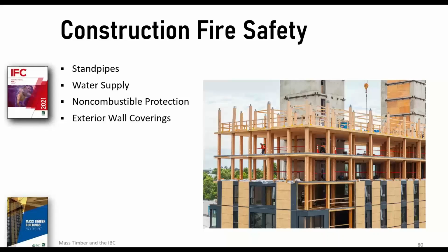Even though the statistics apply to light frame construction, and mass timber has an inherent fire resistance and structural integrity due to the mass, the size of the timber elements, the potential risk of fire in combustible construction was considered by the committee. And they came up with a couple provisions that apply only to mass timber. I'm going to go over all of the new provisions that cover mass timber.